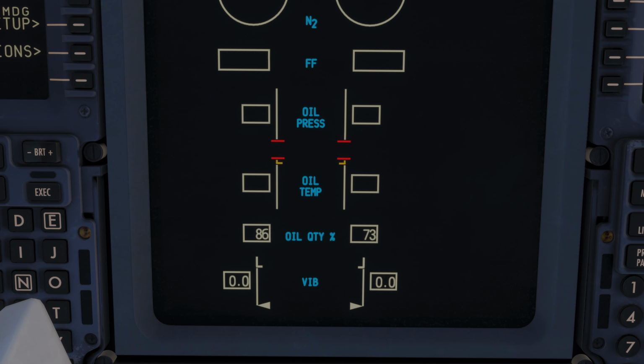For example, one fan blade may have caught a little rock during a landing. There is a small bit of damage which the engineers can easily correct for, and then the engine is started again. Now we will have an imbalance between two parts of the engine that are moving. That means the engine is going to start vibrating. This vibration is tolerable and absolutely normal during engine operation.